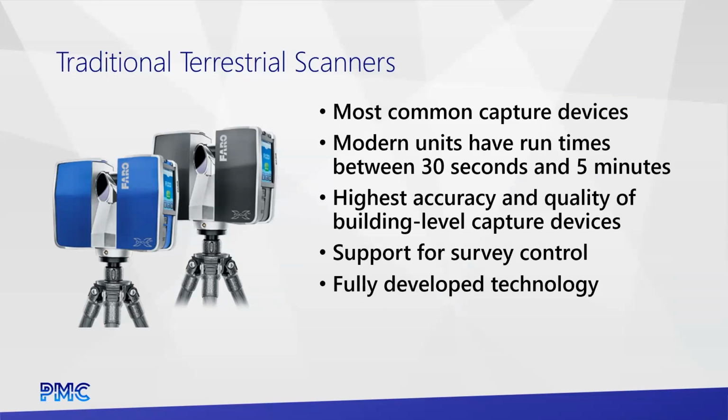Looking at the terrestrial, the tripod-based stuff, this is the oldest technology in this business. It's the one that's used the most still. Just reliable, high accuracy stuff. Nowadays, this is very easy to use, especially on smaller projects where you can do cloud-to-cloud registration. Those jobs are going to go smooth. You don't need a ton of experience with using them. They also have the most robust processing and back-end support, data interoperability. So you can process Leica data with Faro software and vice versa.